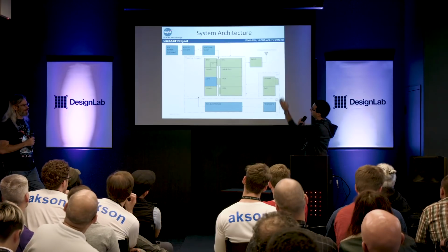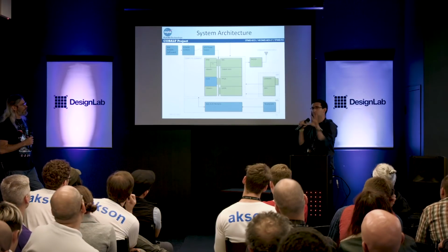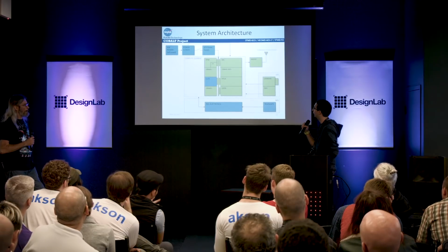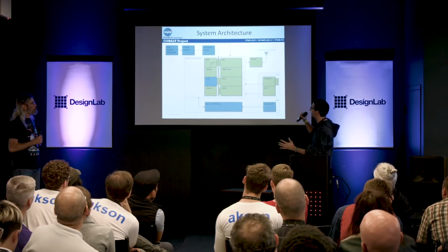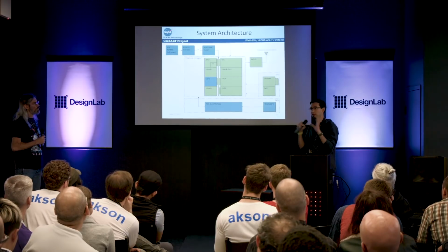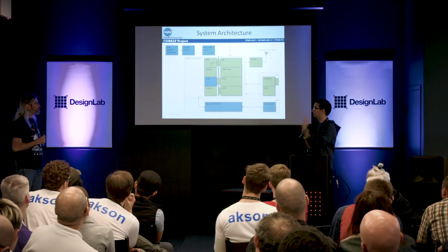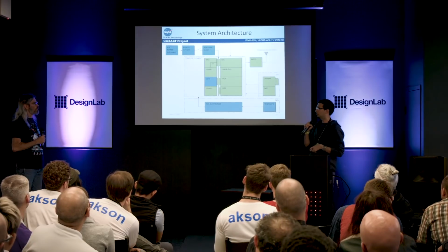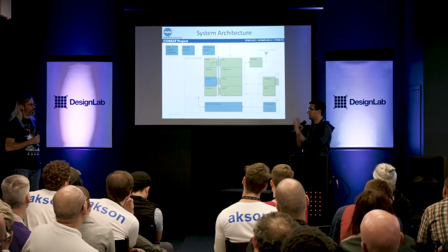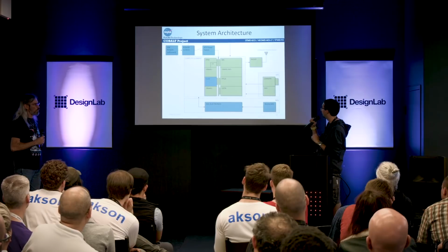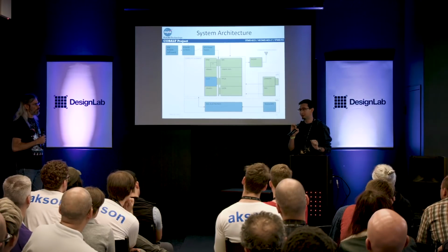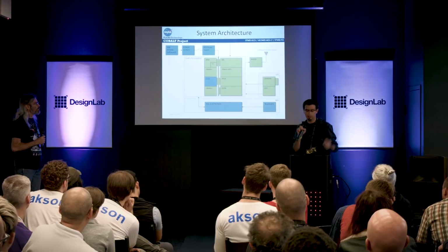These boards are like a single board computer that does a bunch of housekeeping. It's like an i7 processor, off-the-shelf stuff. An FPGA handles all the sensor information coming in and does all the synchronization and all that fun stuff, and then hands it on to a Leon, which is, I believe, a RISC-based architecture processor that does all Steve's magical math that I can't even understand. And it comes out with a beautiful state estimation of where the rocket is.